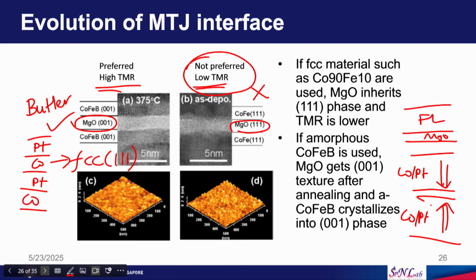Okay, so, at the interface I showed you that there is a cobalt iron boron. You can look at the slides later, but this is something I showed you before. I did not tell you the reason why we have this cobalt iron boron, because that time it was too early to discuss that. The reason we have it here is to break the crystal structure following.